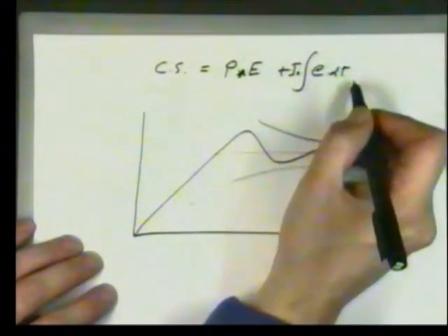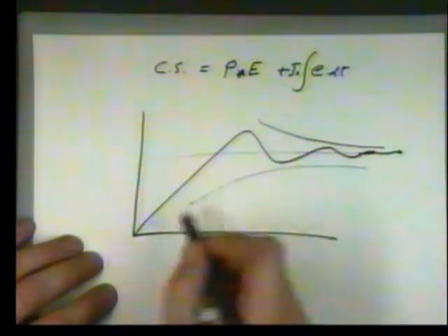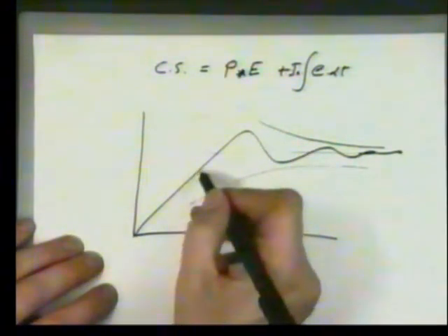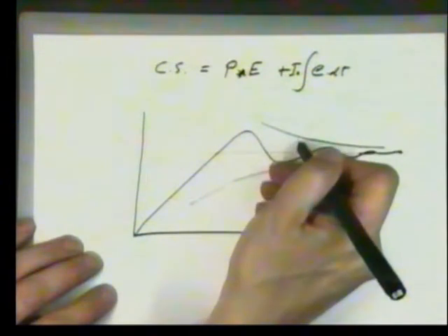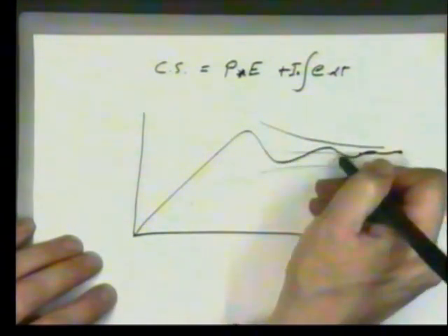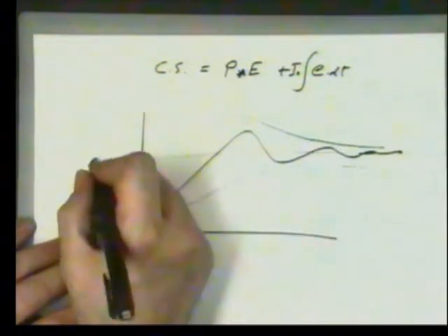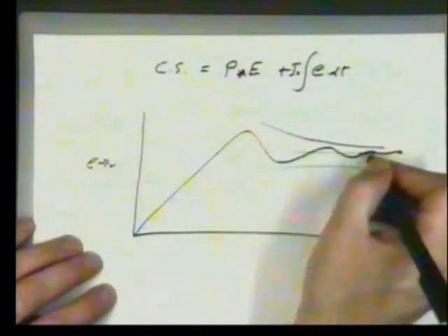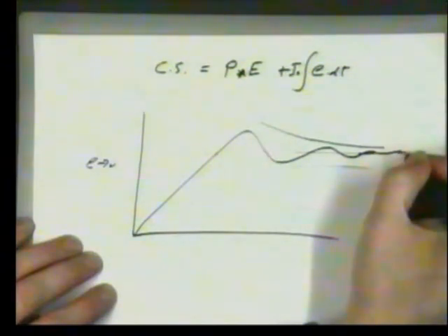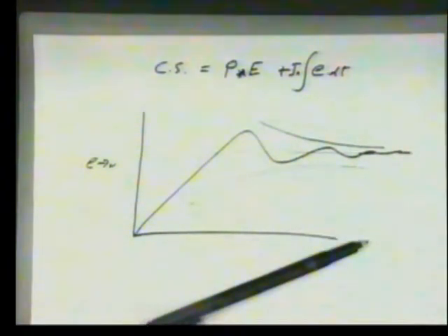So you integrate the error over a long period of time. And what that does is it pulls us out of the steady state error through the set point, and the I term will start dominating when the error tends to 0, and we oscillate around the set point till we finally stabilize and settle out.